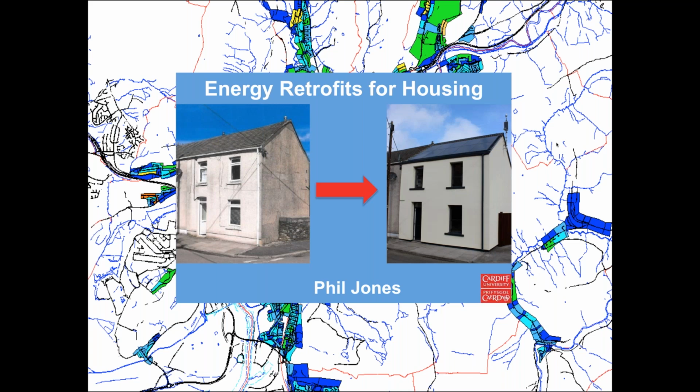So foolproof measures, I'm not sure of any. I don't know of any, but we would always recommend topping up the loft insulation. Even if there's loft insulation there, people sometimes think it's not worth it. But because it's been disturbed or reduced in depth, the top up will get you to the required standard, even if you think it's not worth it. It usually is because of this disturbance effect.